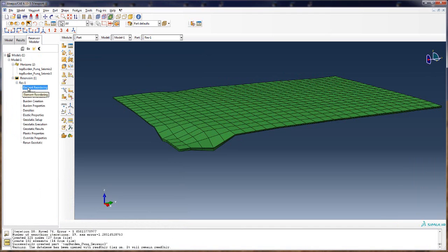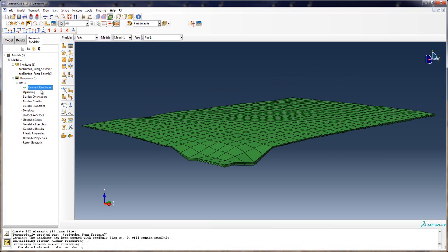The first step in this process is about a 10-11 step process, and it's sequential. We've got to go through here in order to create a model inside of Abaqus, get it run ready, and do all the initial geostatic analysis to ensure that everything's in equilibrium. We have to run through about these 11 or 12 steps. So the first one we're going to do is just perform reordering, and there are no options to that. It's just a step we have to perform.